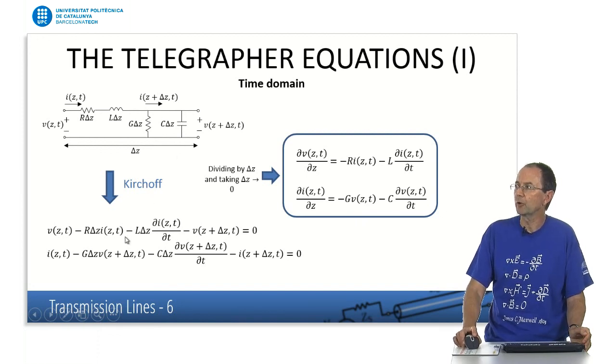So when we equate here the voltage and current intensity equation, then we can take spatial derivatives, just by assuming this delta z distance can be taken very small. So we can just take a limit of delta z going towards 0. And then what we get here is a spatial change of the voltage and the current can be related with the other parameters, with current or voltage here.